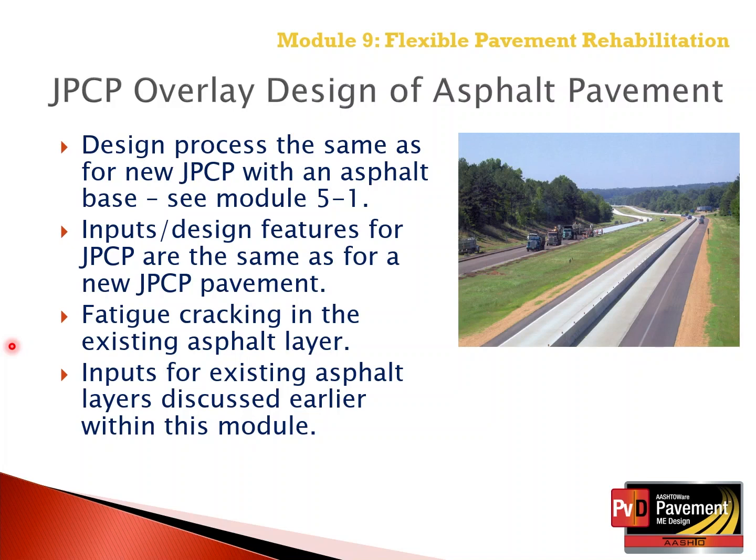And this was discussed and described in Module 5-1. The inputs and design features for the jointed plain concrete pavement overlay are the same as for a new JPCP. The difference is we have fatigue cracking that's entered for the existing asphalt layer.